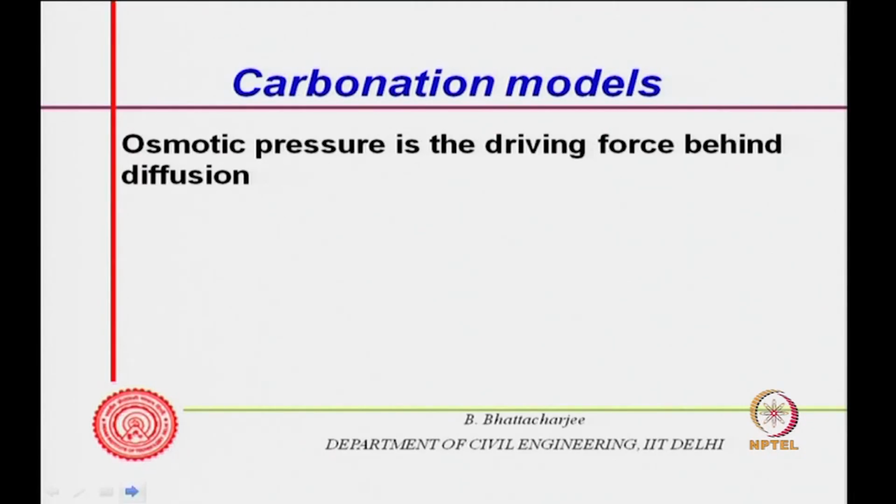Now, what is of our interest is the carbonation depth. If I call x as the carbonation depth, this is important for us, right, and we do model this carbonation depth, because when the carbonation depth reaches the reinforcement level, that is the time depassivation can occur. So, therefore, service life with respect to carbonation will be defined when carbonation depth has reached the rebar level or more. All right. Now, how does carbon dioxide come?